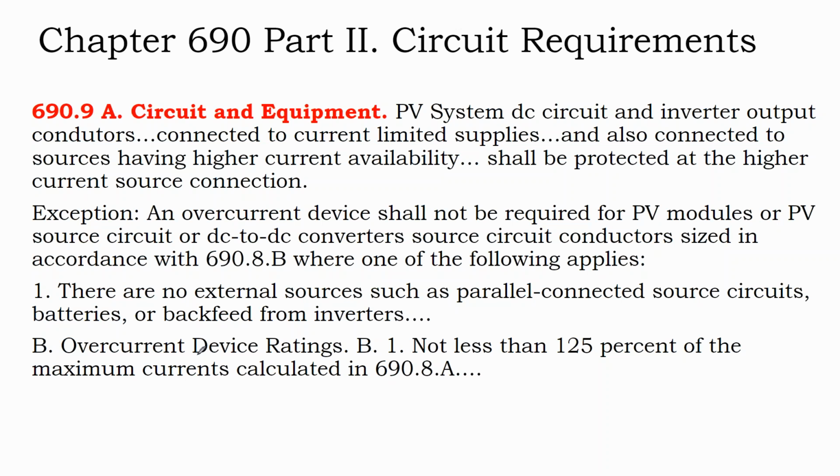Do I have overcurrent protection on the other side of it? And if not, if there's no breaker regulating that source, then why is that the case? It might be, well, because I'm doing a tap and it's 10 feet away from the source. So that means if something's going wrong, I'm already right there at the source, which has its own disconnect switch, and I can just turn it off.